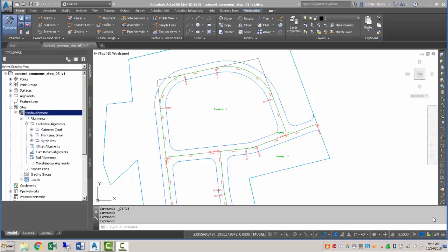Now that we've got our subdevelopment site with all of the alignments already set up and the parcels divvied up based on the right-of-way, we want to move on to the vertical curves. So we've got roadways here in a horizontal curve fashion, and they're called alignments here in Civil 3D. And now what we want to do is deal with the vertical curves, which is going to give us the elevation details along this horizontal curve.